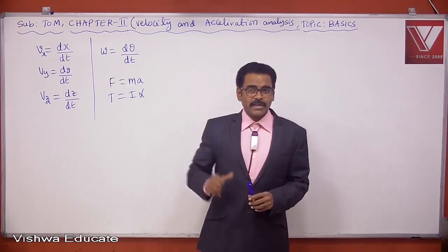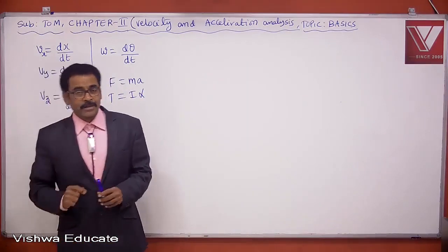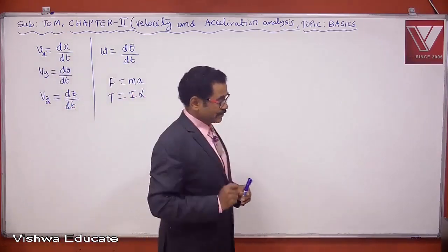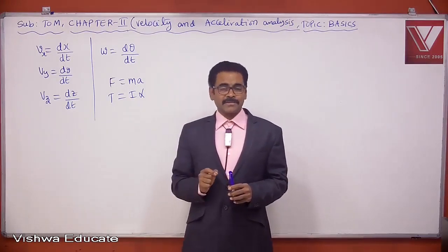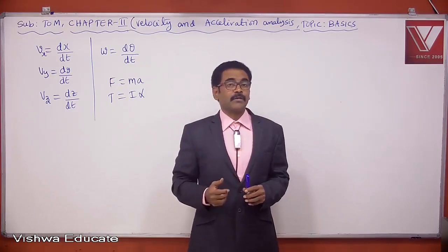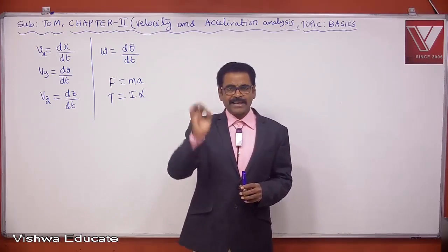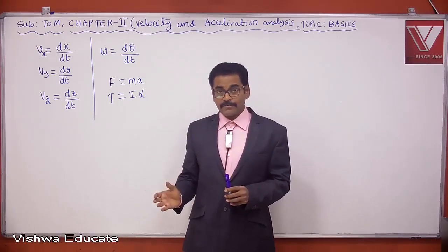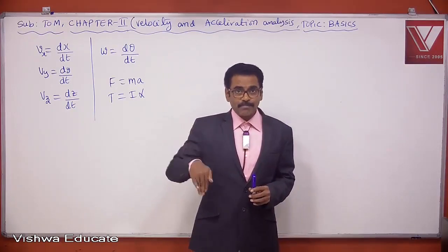If any unbalanced force is there in the mechanism, it may result in vibrations. If any unbalanced turning moment is present in the mechanism, it may induce vibrations. Vibrations primarily come because of either unbalanced force or unbalanced couple.